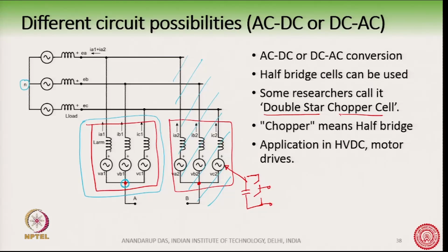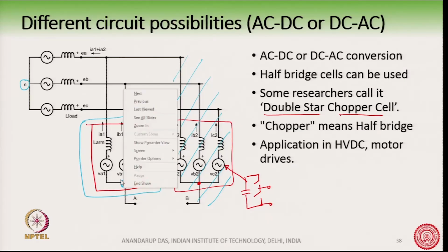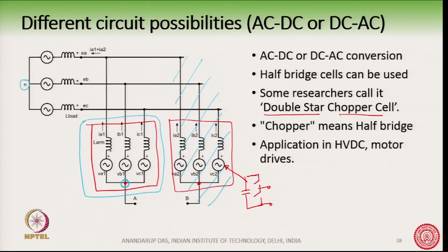We also understood that during fault condition, the voltage difference between this neutral point and that neutral point makes it possible to produce balanced line voltages in spite of having unbalanced pole voltages. So, there will be a voltage difference between this neutral point and that neutral point here.